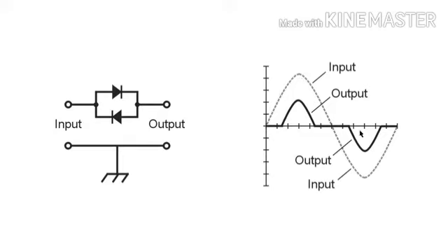So you get again a distorted waveform, but if you're listening to Morse code signals, that distortion is not a particular problem. In fact, it's oftentimes a desirable thing to have a little bit of nonlinearity in the audio circuitry of a Morse code receiver, because if you listen to a pure sine wave audio signal for a long period of time, you can get considerable hearing fatigue. So this is another technique.